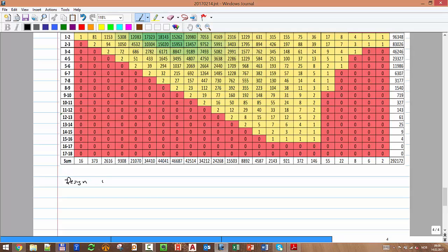Design is usually made using values for longer periods than usually measured. You can usually measure, let's say, 15 or 20 years. If you're lucky, maybe 50 years. But if you want to make your design very conservative, for at least 100 years, and you don't have measurements for longer periods, you need to perform an extrapolation.